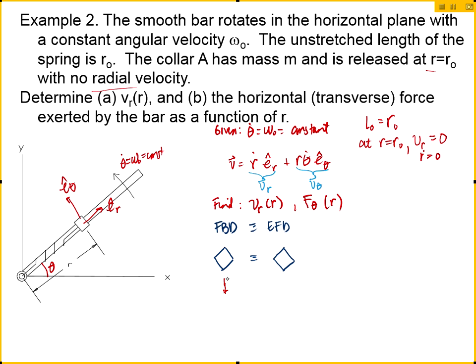Is gravity going to show? Usually it does, right? Read the problem carefully. So it rotates in the horizontal plane. So this view that we're looking at here is actually the top view of the picture. You agree? Yeah, so the gravity is actually going into the page, right? Okay, because this is the horizontal plane according to that. Yes. So gravity is not to be shown.